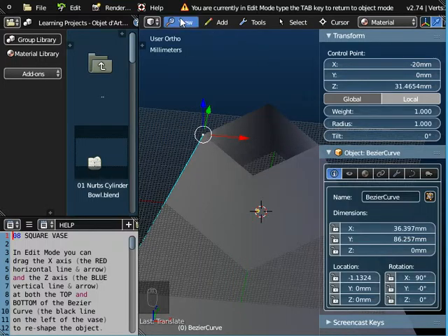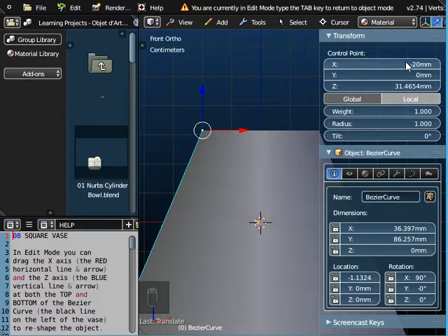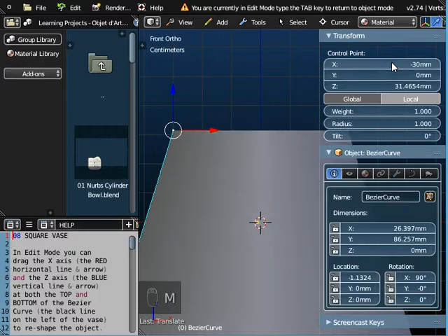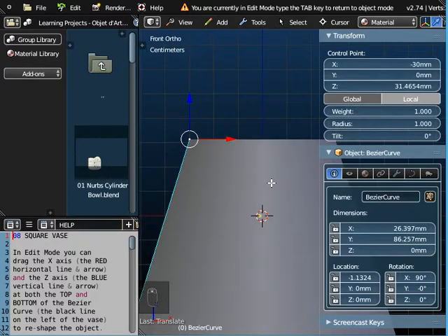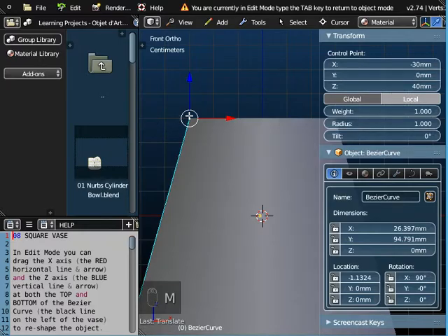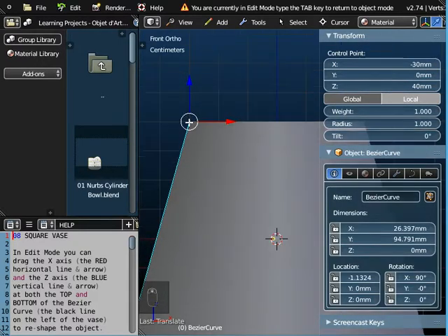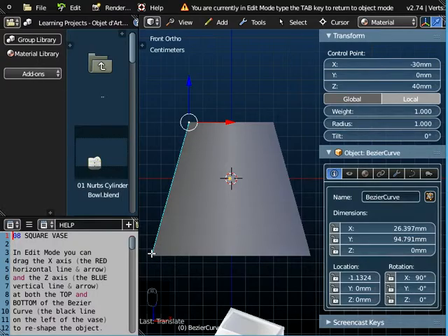If we go to View and Front again, if we wanted it as 60 millimeters, we'd go to minus 30 millimeters. So you do need to remember the minus there. Now this height at the moment is, 1, 2, 3 centimeters, so 30 millimeters. It's just over 30 millimeters. If we wanted an exact height here, let's say we wanted 40 millimeters, we could type 40 mm, and notice it now goes to the point on the grid. We could do the same with the other point as well. So let's see, it's at minus 54.